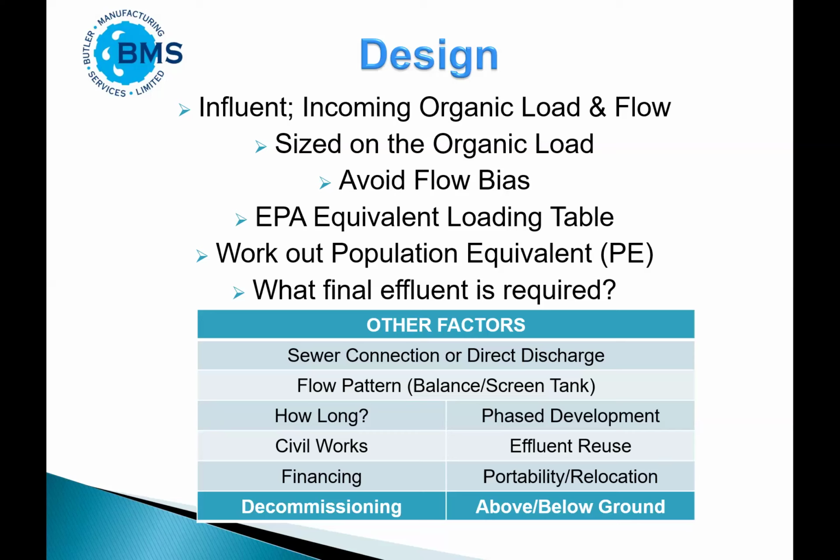Is it going to be a phased development? A lot of housing and a lot of commercial is phased development, which means that you may not want to put in the full amount of sewage treatment at once, but match the phased development. So instead of maybe two 500-person systems, you might put in four 200-person systems over time to spread the cost.